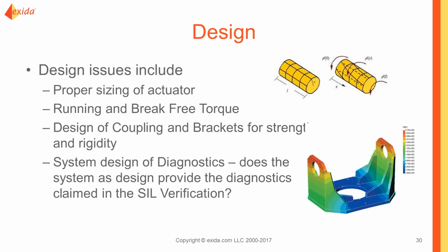I want to pause a moment and talk about design. So design is an important thing. We mentioned the breakaway torque. There are going to be design requirements for things such as couplings or valve stems, and ensuring that you're not over torquing a valve stem. Of course the valve manufacturer is going to have a design guide. They're going to design it, but not only is there a minimum torque necessary to move the valve, there's also a maximum torque it could take without damaging the valve or the stem.